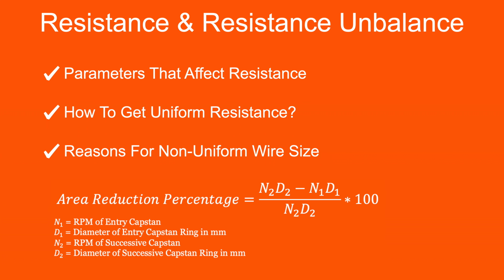But while doing so, we should ensure that before grinding, we should build up a layer of hard metal on the ring by way of welding and then grind it back to the required diameter.